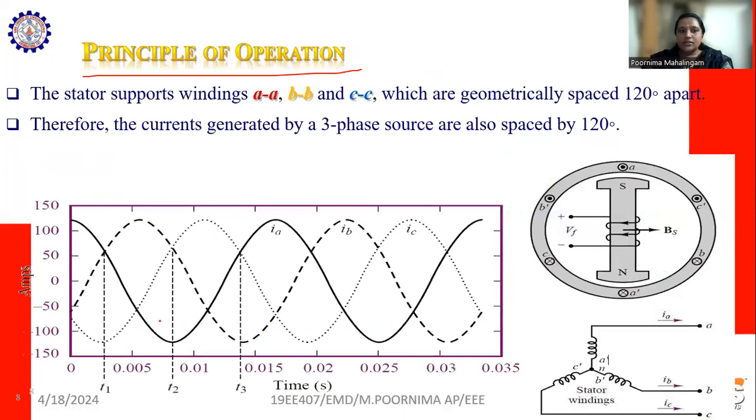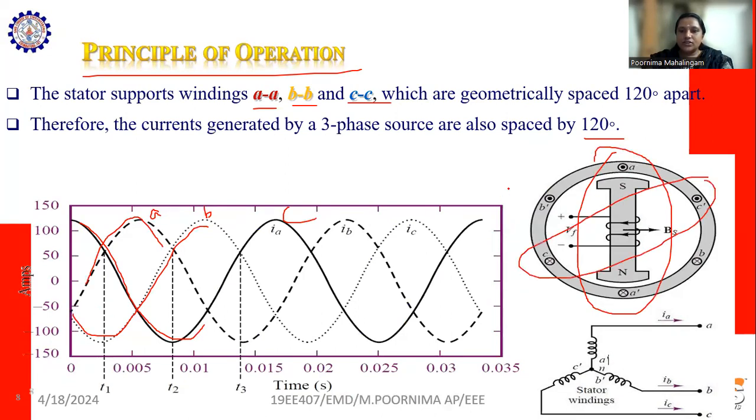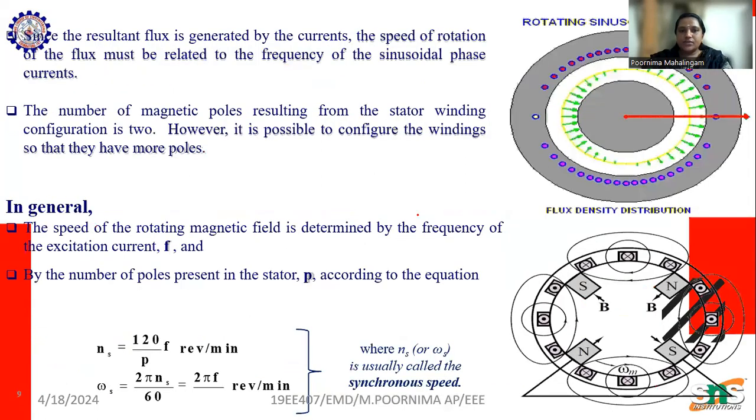The stator is supplied with windings A, B, and C, the three-phase winding, with a 120-degree phase shift, and we can see with the star connection and delta connection how the waveforms go. This is phase A, phase B, and phase C. Here we have one single phase A, and it is shifted by 120 degrees to phase B and phase C. In general, we are seeing three phases.